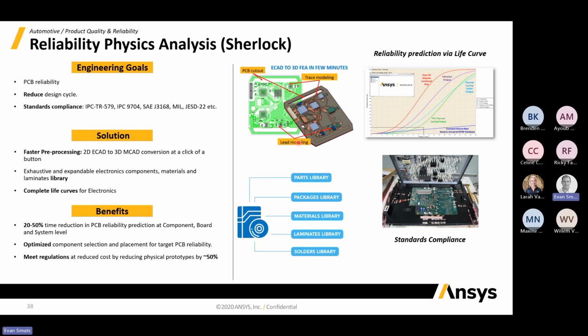And so the idea is that we can then, with something like what we're highlighting here with Ansys Sherlock, specifically look at the PCB board level with the actual components on the board. And so the idea is we can then actually identify specific components and estimate whether those components are going to be failing or not. Maybe a particular chip is sitting in a hotspot on the board, and maybe it's running out of its design temperature, and it will then fail because of that. And so we can identify that on a component by component basis.